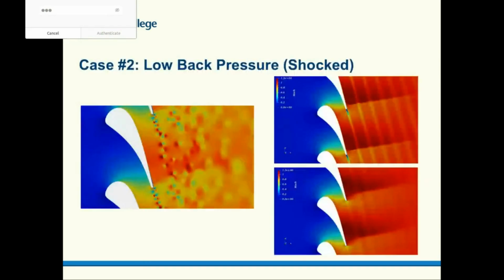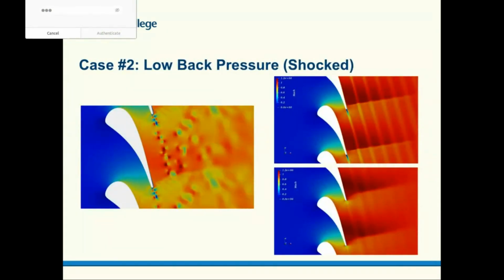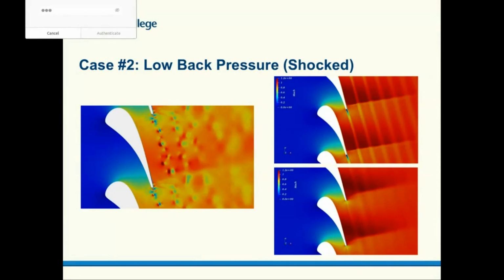simulations? So, for example, these are very expensive, so for example, this one we're still trying to get to work in 3D. And you can imagine the axial chord of this particular geometry. So the axial chord is from the leading edge to the trailing edge. So if you imagine a line like that, it's not the true chord because it's at an angle, it's the axial chord. It's about 3.7 centimeters, so it's a really short thing.